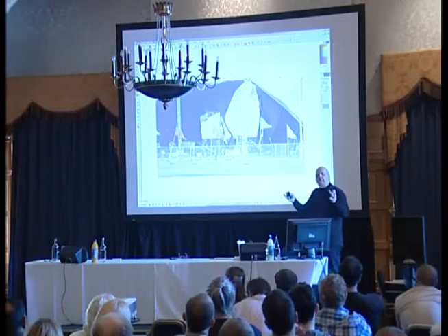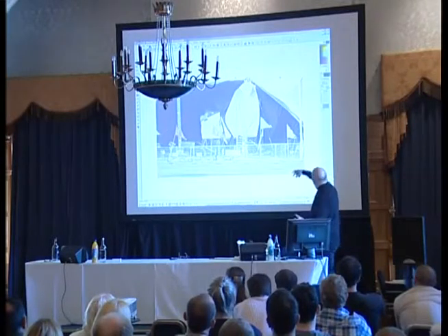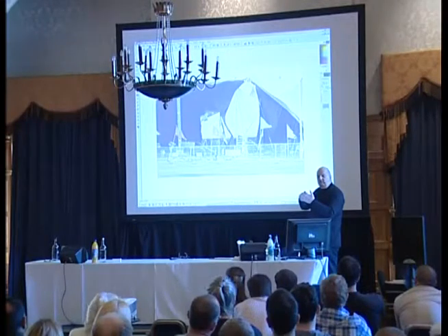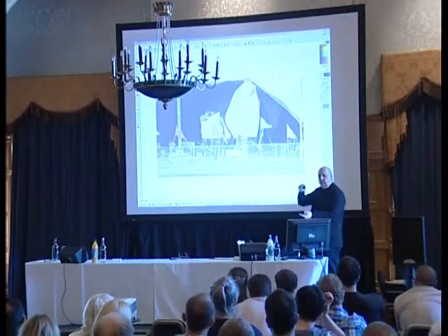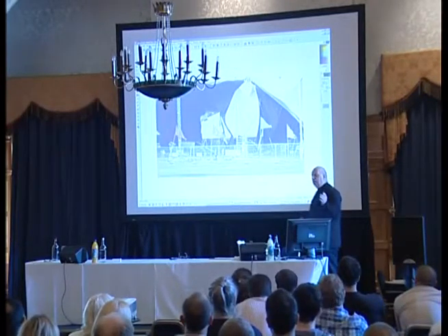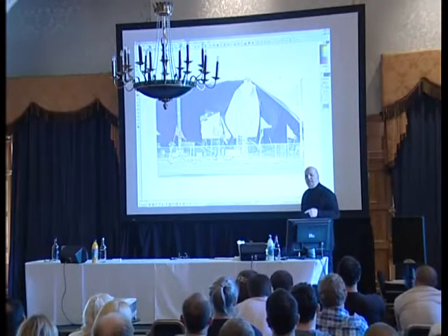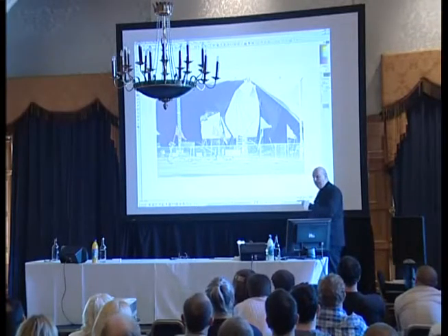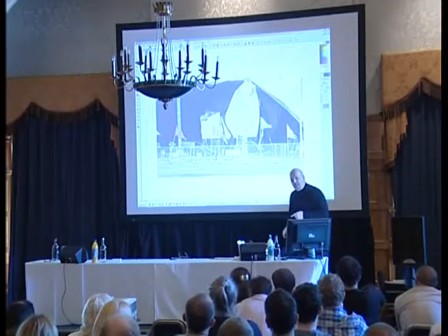Not a lot, not banging about. But if you don't, and the bell ring that lifts the membrane up leans against the king pole, you can damage the king pole enough for it to fail. So it's a pin-jointed mast, you might as well just let it move. So I've seen safety officers on site insist that the contractor tighten them up, and they were actually giving false advice. Now that really should be in the tech book, in the TDS technical handbook.